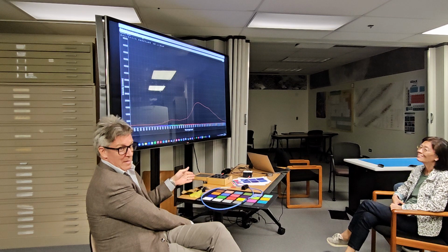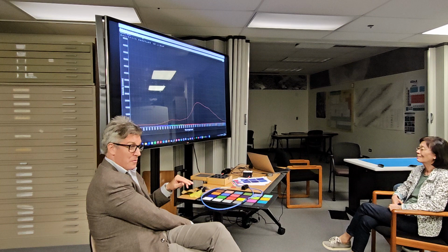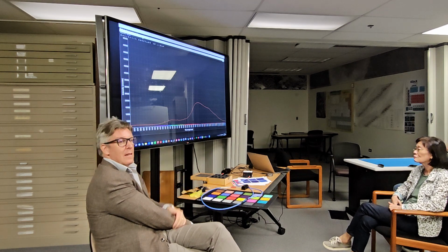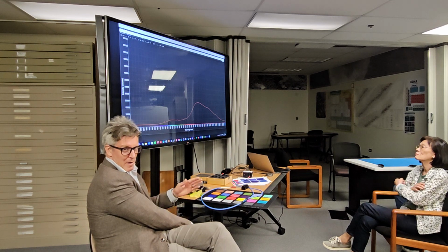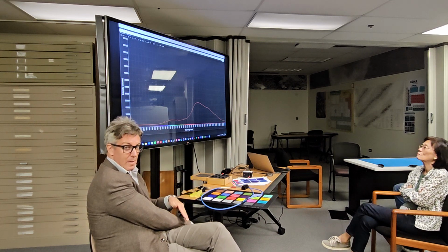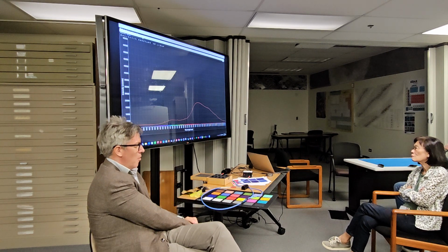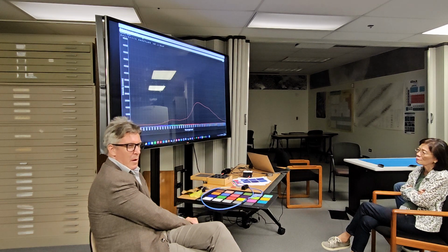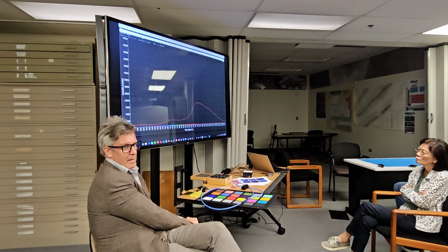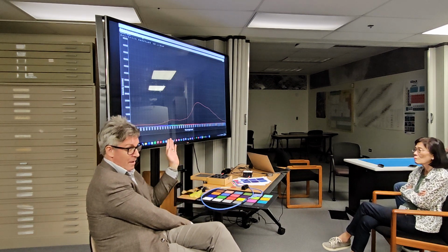So this is a 16-bit system, where the analog digital converter in a spectrometer quantizes, right? Quantize means to break up into small pieces. It quantizes the incoming signal into about 65,000 different levels of brightness, where 0 is none, and 65,000 is the top. A lot of spectrometers use that, although in satellite data quite often people use an unsigned 16-bit integer. Unsigned means I only have positive numbers. It goes from 0 to like 65,000.